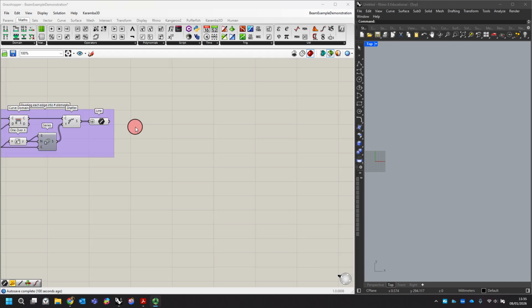Okay, so the next thing that I want to do is for each line or each element, I need to define the start and the end points, and they're obviously going to be my nodes. And then the final stage in putting everything together for the mesh initially is I need to generate a unique set of elements and a unique set of nodes, and I just need to make sure that there's some consistent numbering on all of them.